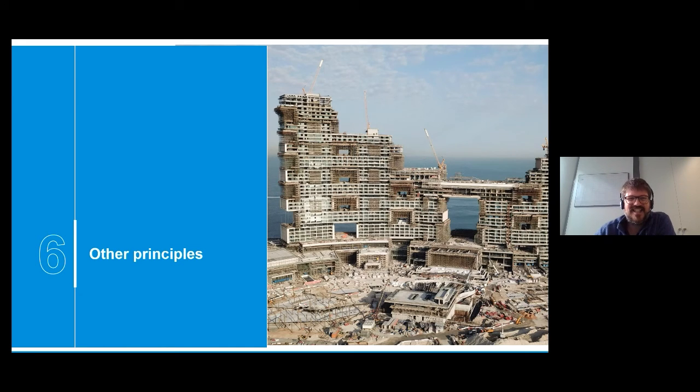Okay, and I know that this tower is very high, and there is a different temperature at each level. What do you do for that? Do you have a different mix design at different levels or not? It's a really good question. Actually, we usually consider that we lose 1 degree per 100 meters of altitude. So we know that we will have 8 degrees less at 800 meters. This can be negligible, but actually it will help us, because the concrete is already quite hot when we do it, because in Dubai the temperatures are really high. So it will help us a little bit to slow down the reaction.